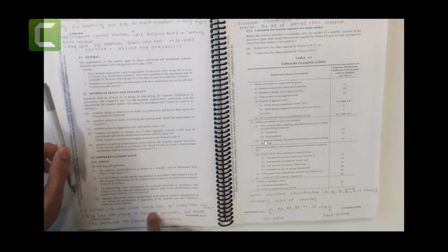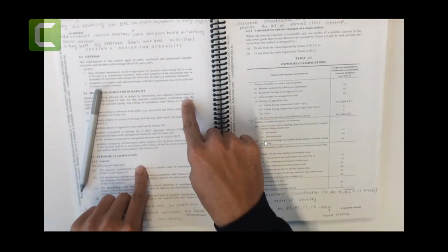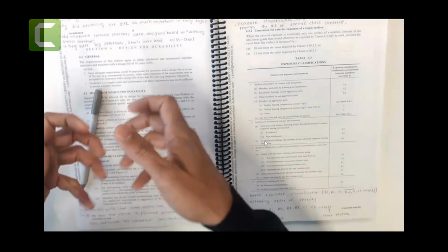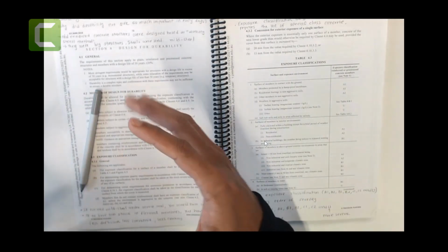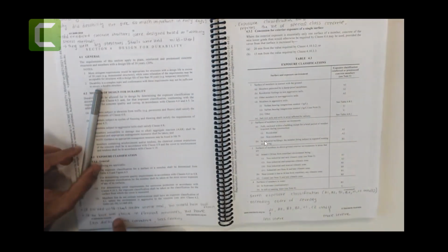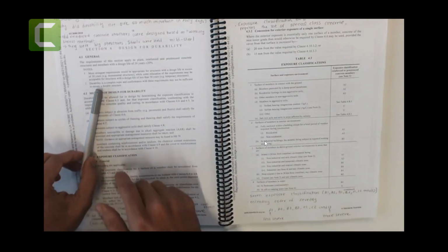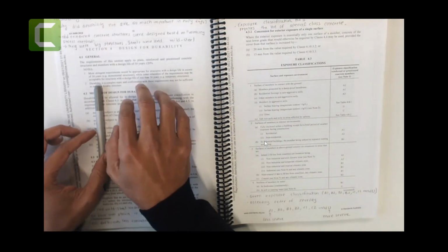If you use mild steel under service load, you will have low stresses. Those old, very bulky structures have very small strain. They don't deflect. They are very rigid. With low strain you have less deflection, less curvature, and less cracking, so you will have no cracking. In those days the columns were so big that they didn't make these durability checks.